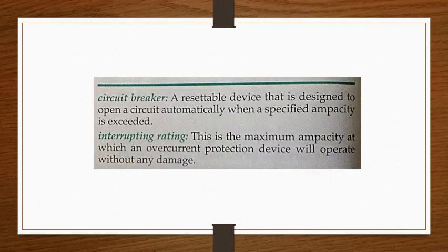Breakers. A circuit breaker is defined in the NEC Article 100 as a device designed to open and close a circuit by non-automatic means and to open the circuit automatically on a predetermined overcurrent without injury to itself when properly applied within its rating. See figure 8-10.